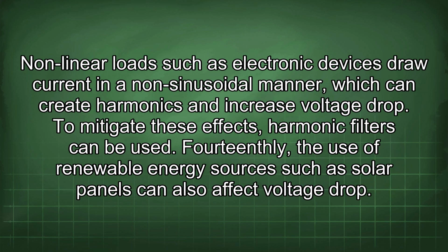Thirteenthly, the presence of nonlinear loads can also affect voltage drop. Nonlinear loads such as electronic devices draw current in a non-sinusoidal manner, which can create harmonics and increase voltage drop. To mitigate these effects, harmonic filters can be used.